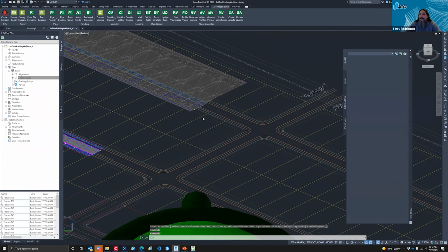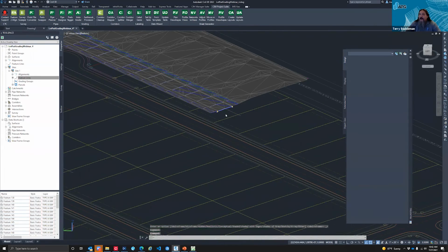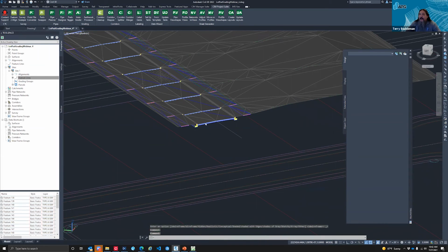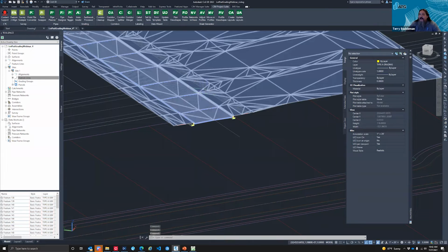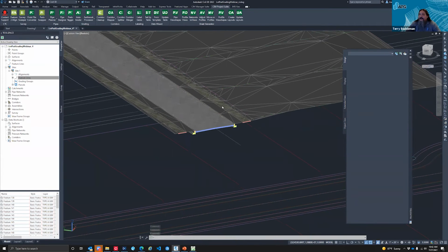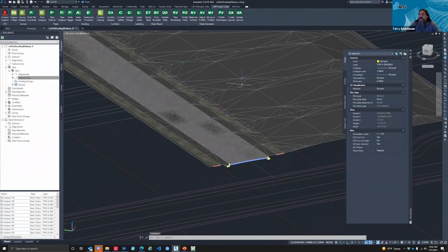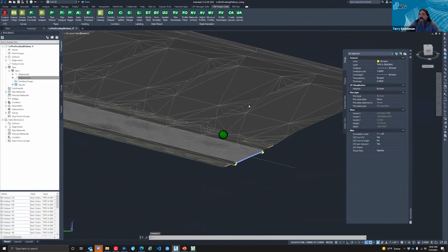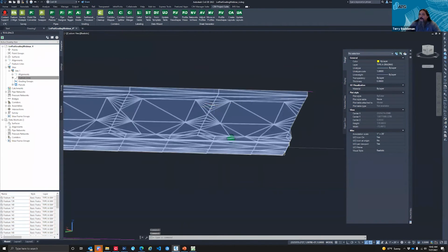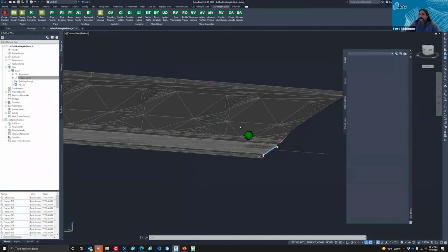All right, so here we go. We have our roadway corridor. Right now, we're just showing curb and gutters. We can turn on our targeting for our Corridormapper on here just to see what it looks like. We have our driveway slopes going down and our pads, and we can see on our lot lines our pad here, and it's sloping down on each end because our slope that we're tied in here is a little bit lower than our pad, and it's went and graded those out.